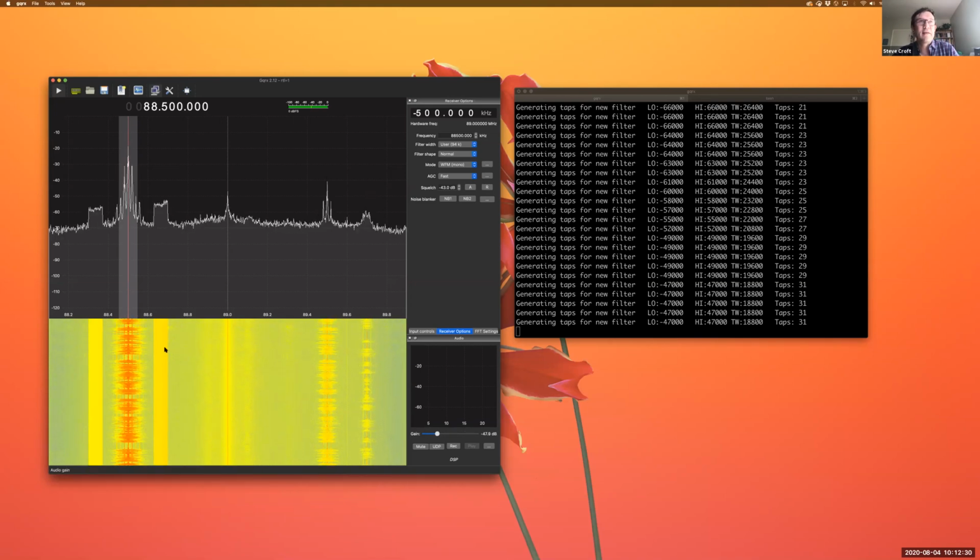But you can see even with this digital signal, where I don't have my decoding set right, I can still see that there is information there. And even though it looks noise-like, there's the Nyquist theorem, which tells you there's a fundamental limit in terms of how much information you can pack into a certain bandwidth. If you pack the maximum amount of information in there, it will start to look very close to noise, because the entropy of the signal is going up. But even though there's a lot of information packed in there, and even though I'm not decoding it, I can also see these sharp edges, which obviously look artificial.